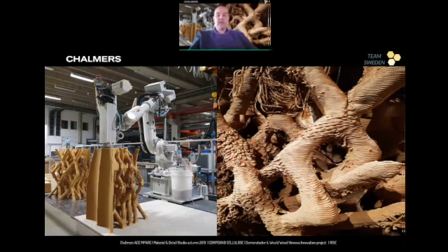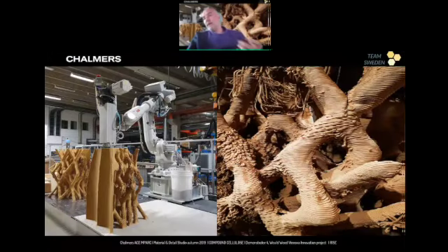And as you see here, we couldn't really do exactly what this doodle nest set out to do. So in a way, we have a much simplified structure here because the material, when we scaled things up, didn't behave in a similar way enough from how it behaved on the smaller 3D printers we had. So when self-weight became a central issue for the material, we had to simplify the structure a bit into this tessellated structure that you see here.